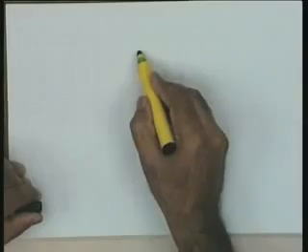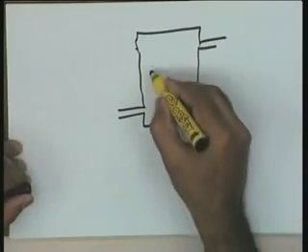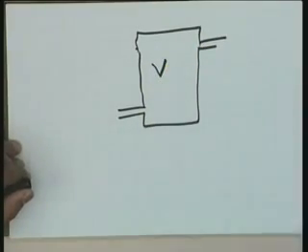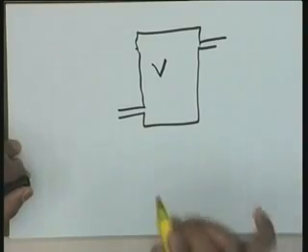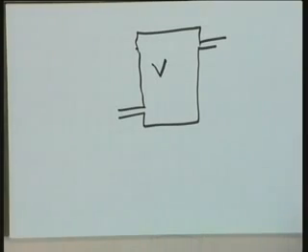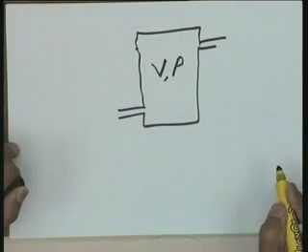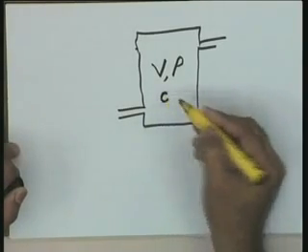Consider, just a couple of minutes are available with me, and therefore, I can write the tank also. This is your tank. This tank has got volume V. Please give me the equation now. If you got my point, you can give the equation to me. What is the thermal capacitance of the liquid in the tank? If I get it from you, it will confirm that you have understood my point. I want from you the thermal capacitance of the liquid in the tank. Okay. V is the volume in meter cube, rho is the density in kilogram per meter cube, and C is the specific heat.